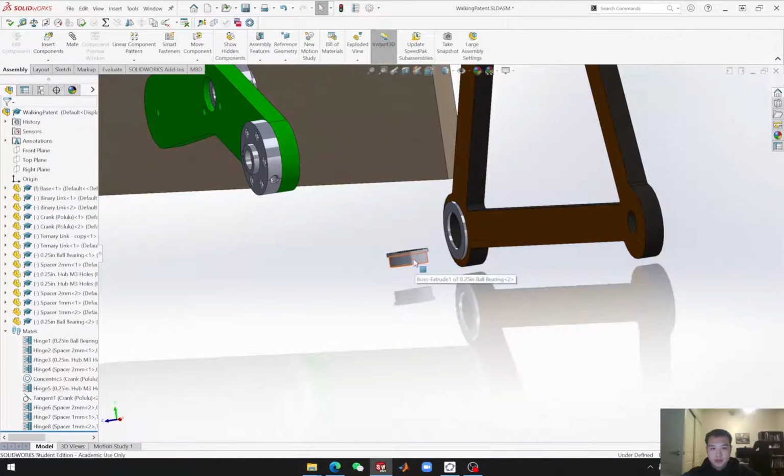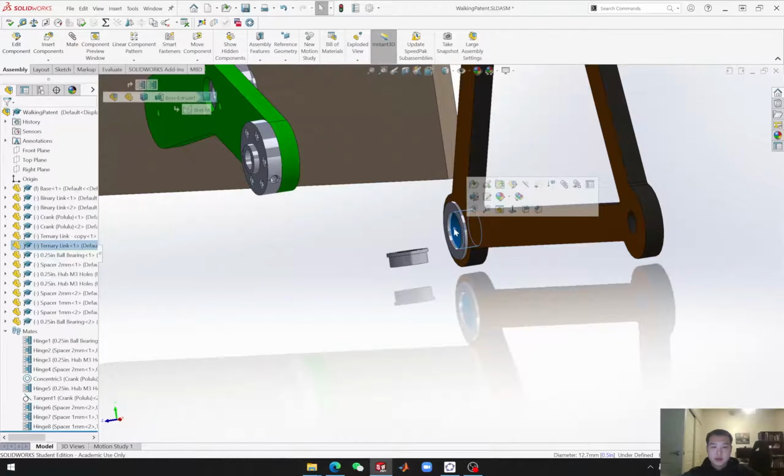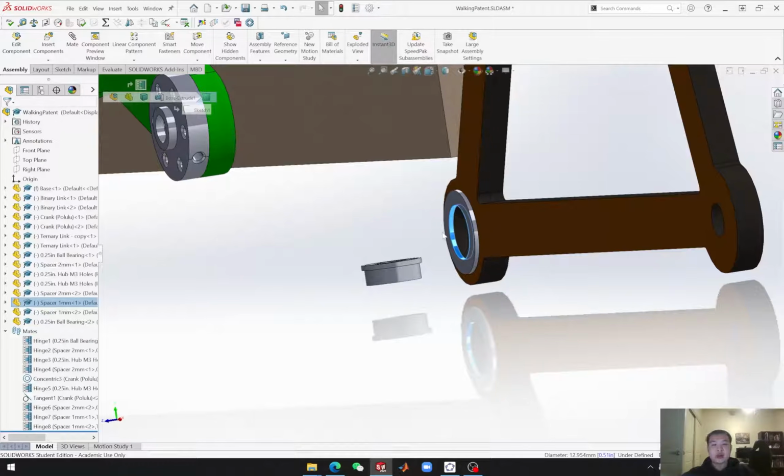This is because the size of this hole, you can see it's 0.5, and the spacer is also 0.51. The size for the spacer is a little bit larger than what we need because the spacer will be 3D printed. If we're gonna manufacture this model, the spacer will be 3D printed. So the actual size we get from the 3D printer will be smaller than what we design.